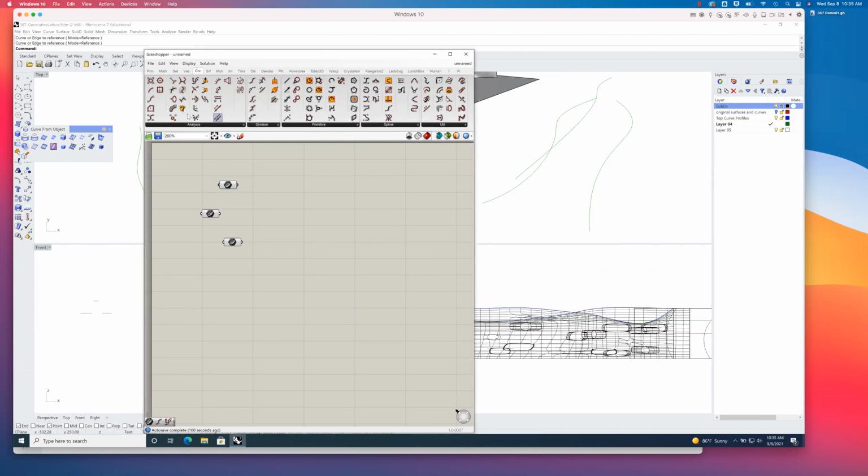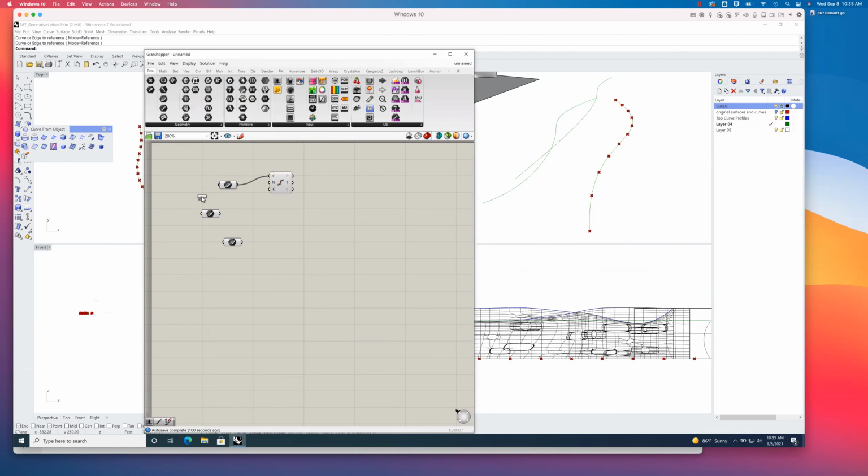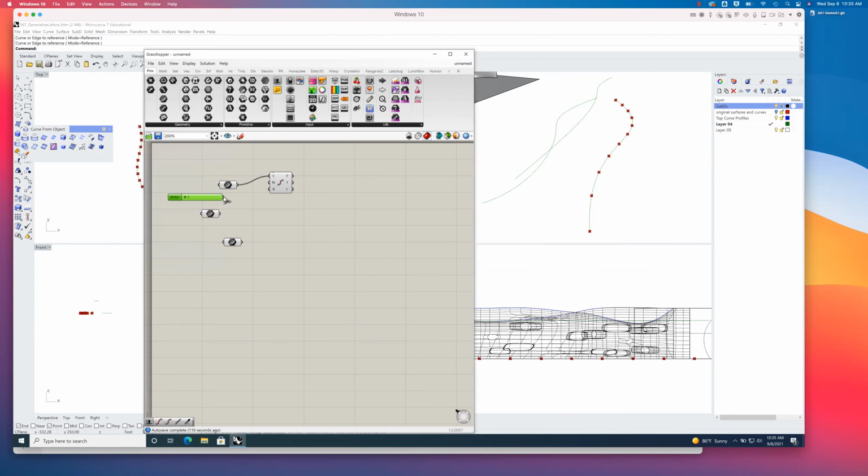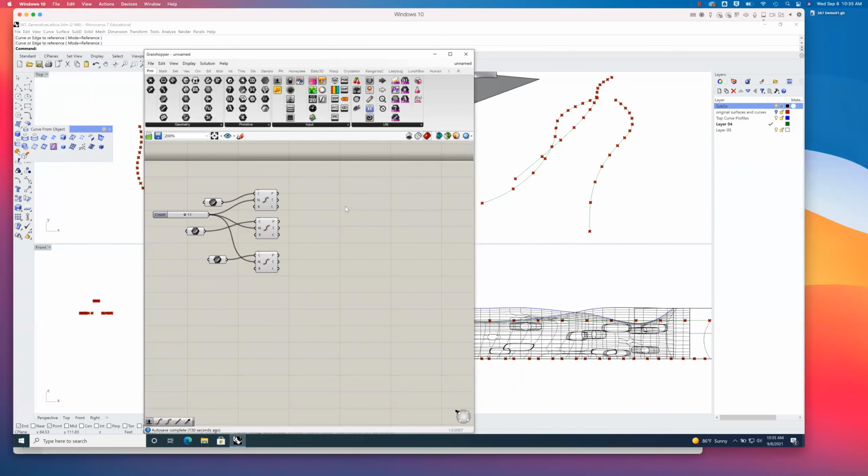And not a big surprise. Let me go ahead and do that really quickly. Divide curve. There we are. Let me go ahead and make a slider. Constrain this to integers. Set minimum to 1, maximum to, I don't know, 30 or whatever it would be. Now I'll copy, paste, paste. I'll plug this curve in and this curve in. Yep, there we are.